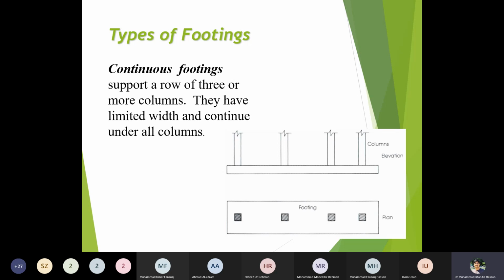And of course, this footing is good in case of continuous footing. There is another type of footing which is linked with this, a footing beam. I can join all the columns by a footing beam also, and practically I am giving that type of footing also, because that is also another good footing. In this, punching is there, but if I provide a beam from column to column, then the punching is also eliminated. And in case of seismic zone also, this continuous footing plays a good role, because this becomes a grillage footing.